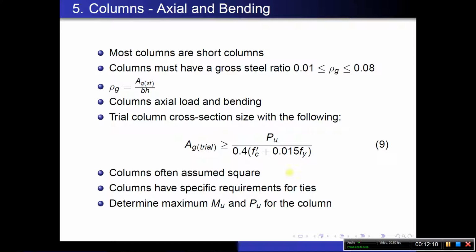Let's now move on to columns. Now, one thing to realize that's very important about columns is that columns will resist, of course, axial loads, but they also almost always will also be resisting some bending loads. And so there is this interaction between those two types of loads.